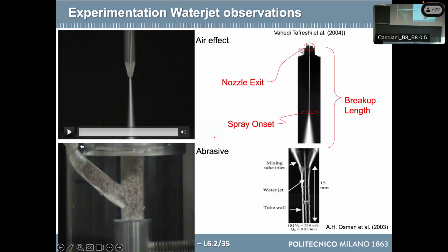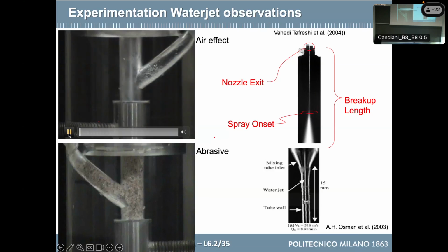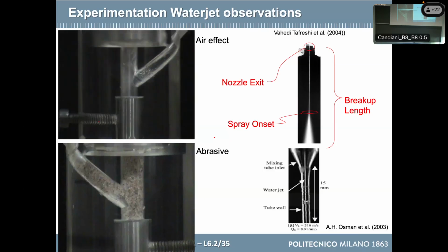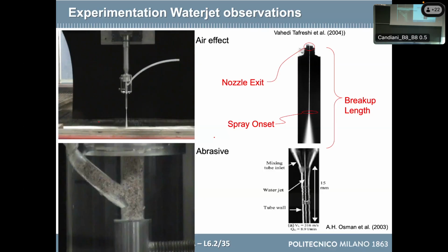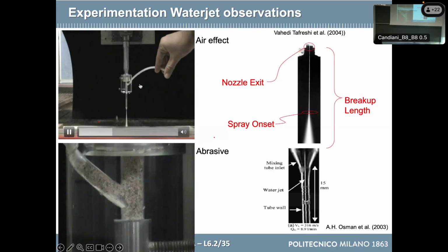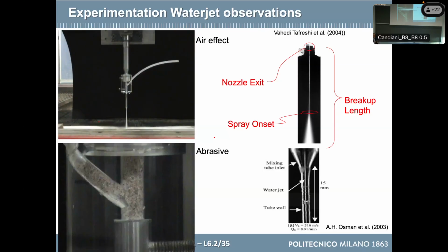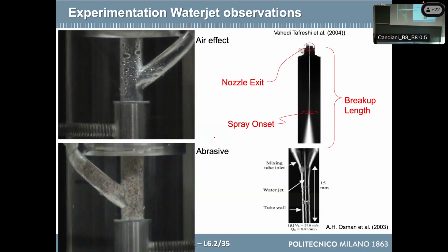And this video is also nice because you can imagine that I risk to clog the abrasive because of those droplets. Every time I switch on and off, those droplets are going around. And since this is the inlet port of the abrasive, if I have abrasive there, the droplets will make the abrasive wet, and I risk to clog the abrasive, which is absolutely detrimental, because if I'm cutting a material that needs abrasive and I don't have it, I break it, especially if it is fragile.